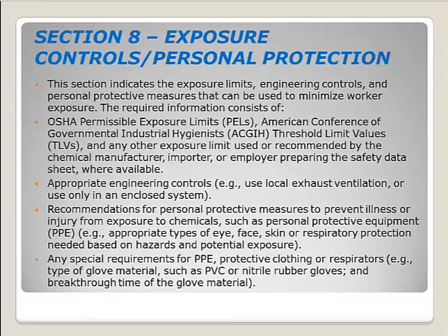Recommendations for protective measures to prevent illness or injuries. Such things as you're talking about eyes, skin, face, respiratory protection. So in these areas you would be possibly talking about the use of respirators and the need for particular gloves, whether they be non-pervious gloves or something of that nature, would be certainly identified in Section 8.